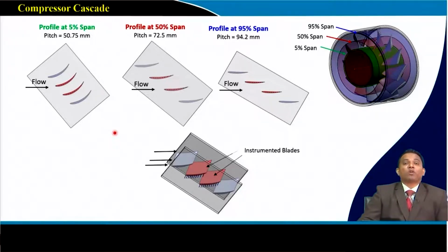We have discussed the C4 aerofoil, the NACA aerofoil, the CDA aerofoil, and the DC aerofoil. All those aerofoils were developed for a particular pressure rise, for a particular kind of CP distribution. So all this data is of great importance.